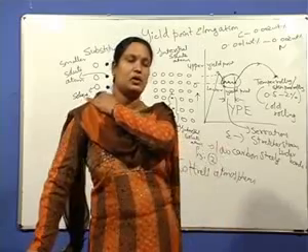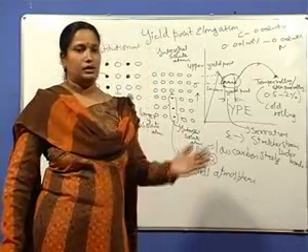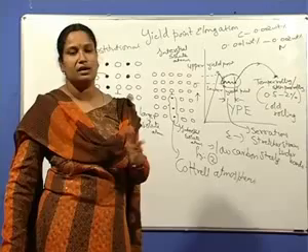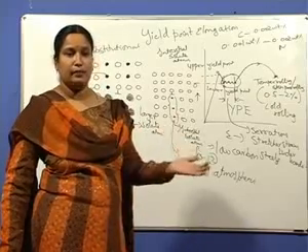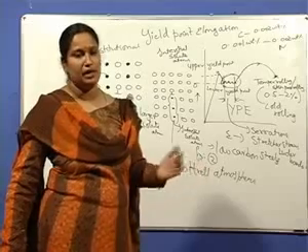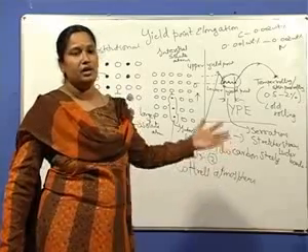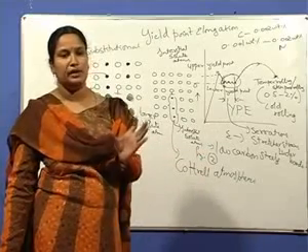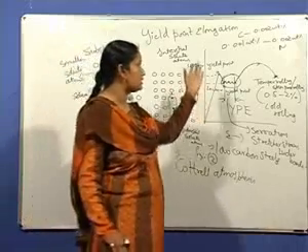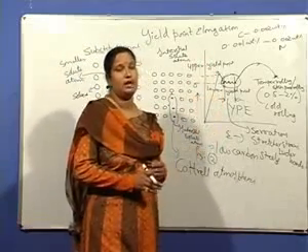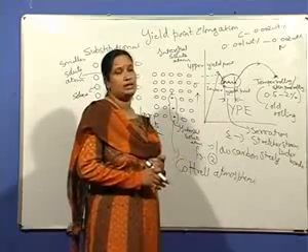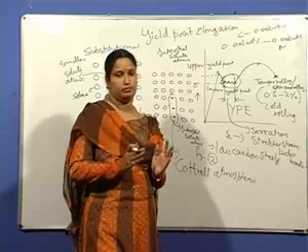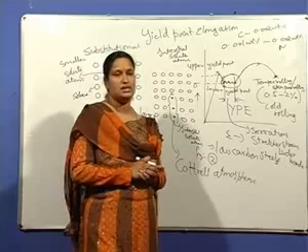So as soon as temper rolling or skin pass rolling is given, these low carbon steel sheet materials are to be formed as early as possible, because if sufficient time is given, carbon and nitrogen diffuse again and cause the yield point elongation. This diffusion of carbon and nitrogen as a function of time and temperature, and the appearance of the yield point as a result of time and temperature, is known as strain aging.